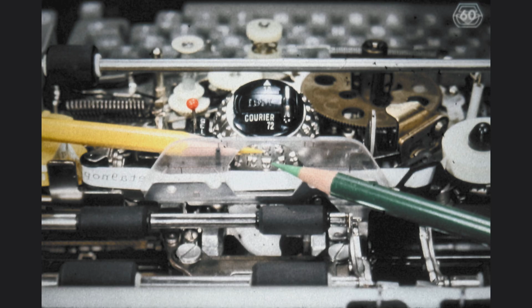It is most important that we allow for some clearance between the cam follower and the actuator when the detent cam follower is in the dwell of the detent cam. If the clearance is not there, it indicates that the tilt detent is not fully engaged with the tilt ring. On the type sample, this problem would show up as poor vertical alignment. We repeat, the clearance between the actuator and the cam follower should be up to 0.25 millimeters.